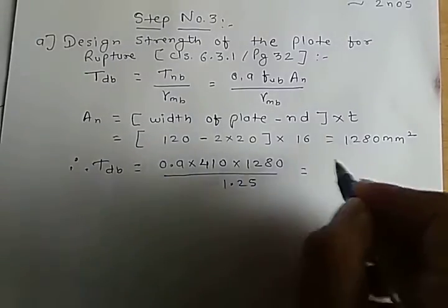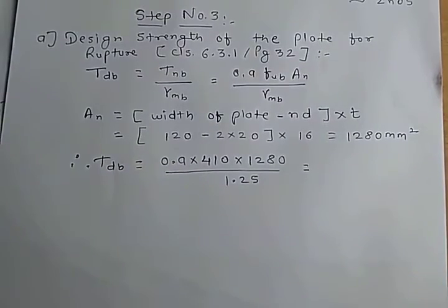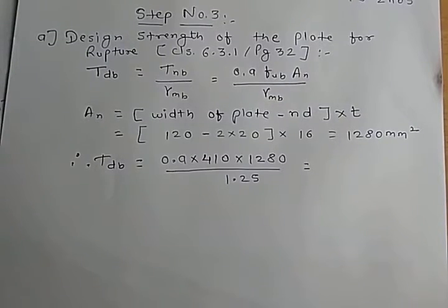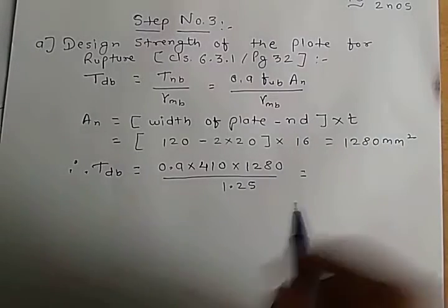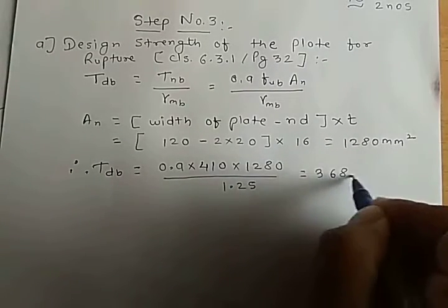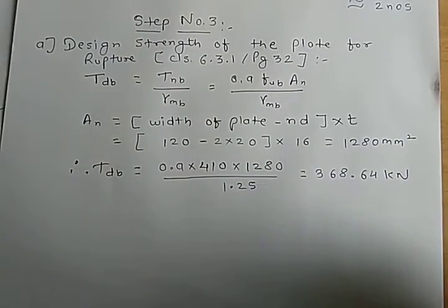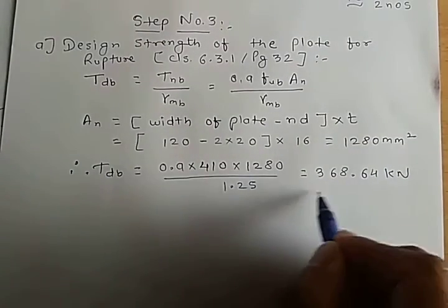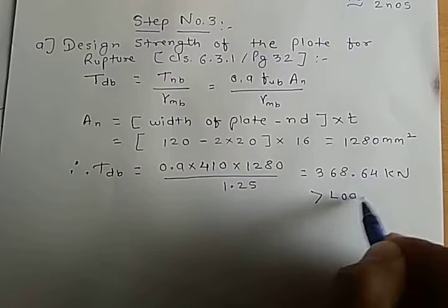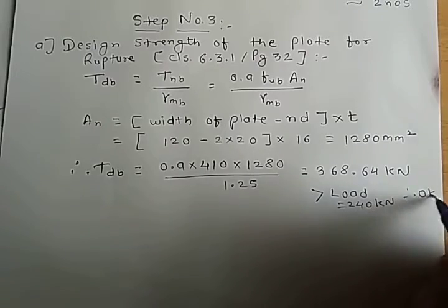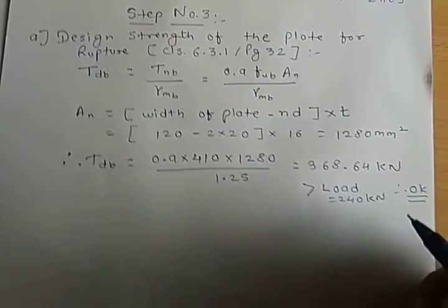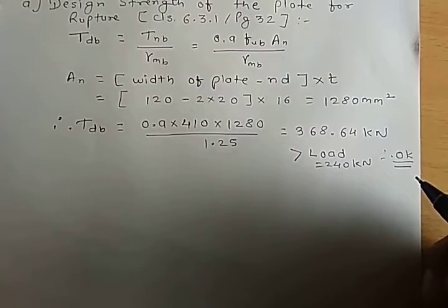If we calculate it, this value comes out to be around 368.64 kilonewton. Now this has to be greater than the load value, which equals 240 kilonewton, and therefore we can say this is okay. So that is safe in the rupture criteria.